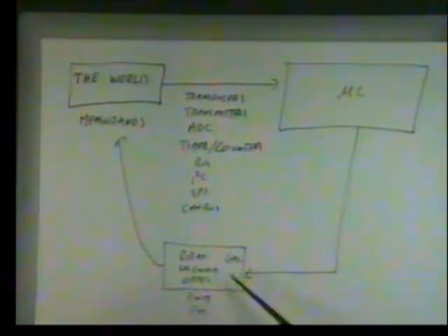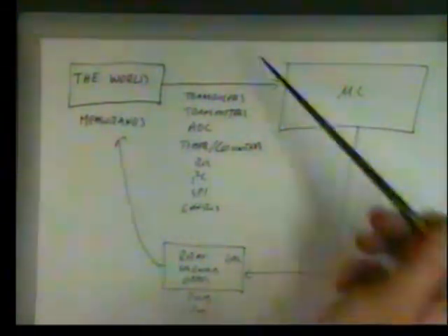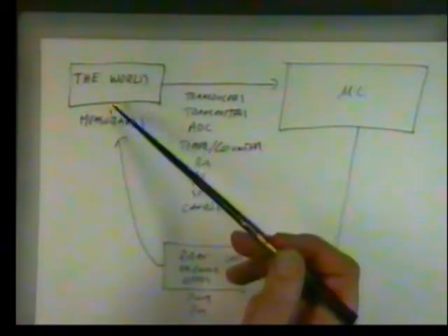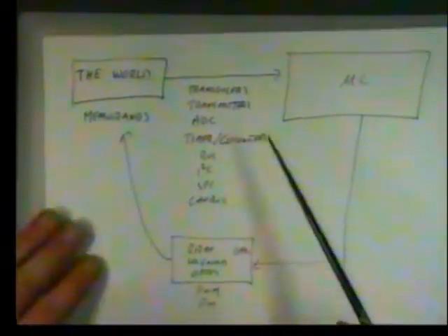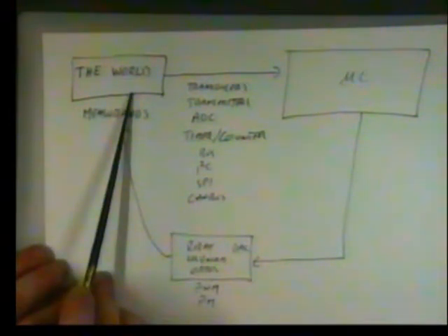Once we've decided what we're going to do, we have these output devices we've referred to: relays, solenoids, optocouplers, digital to analog converters, triacs we've talked about. We've talked about the techniques of pulse width modulation and phase modulation. We've discussed two types of motor, stepper motor and DC motors. So here we have now all of the external hardware techniques. We've covered everything we need to know about how to get information out of the real world and how to act on the real world to drive it back to what we want it to do.